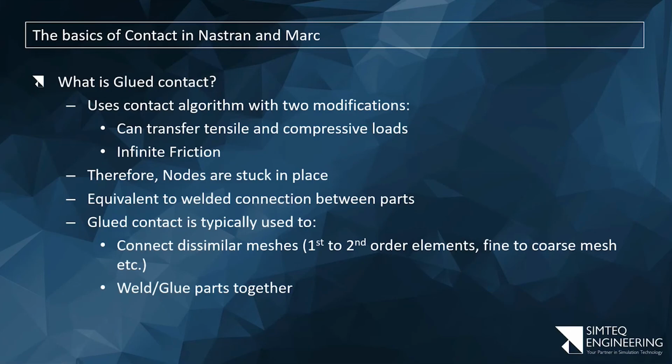If I look at plasticity as an example of being nonlinear, I've got an elastic slope, but the moment it goes plastic, I just go on a different slope, or a slope that slowly curves to a lower stiffness or effective stiffness. Contact is not that forgiving. It simply says there's zero stiffness between two parts if they don't touch, and there's infinite stiffness at that touching location between the two parts the moment they touch.